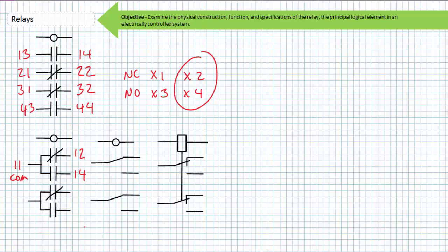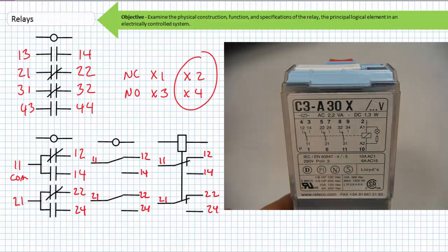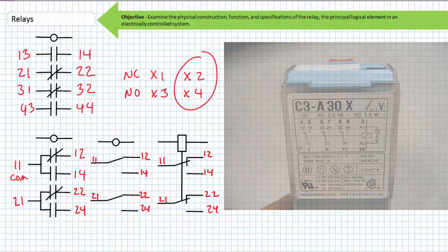The terminals of the second switch associated with this relay would be assigned 2-1 for the common, 2-2 for the normally closed side, and 2-4 for the normally open side. Alternate representations of the schematic would use the same terminal numbers. Any additional switches associated with this relay would continue in this same fashion, starting at 3 for the first digit. If you're ever lost about which pin is which, just look at the manufacturer's datasheet or on the side of the relay itself. Very often the pinouts are printed on the side as well as pertinent electrical data.